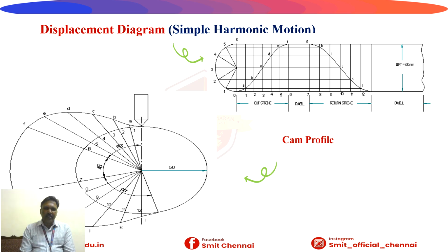The first angle is 60 degree. It is given. You have to take it with a protractor with reference to the vertical line, then followed by 45 degree, then again followed by 90 degree. The remaining angle should be kept as the dwell condition. It is given in the problem.